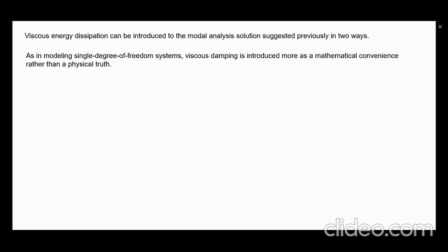The advantage of the viscous damping model is that the equation remains linear. On the other hand, if there are other types of damping involved, for example frictional damping, what we refer to as Coulomb damping, the equation becomes nonlinear if you try to incorporate that directly.